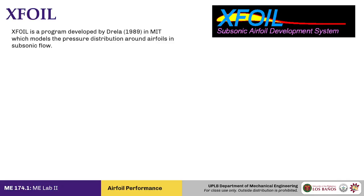It does generate fairly accurate results, especially in the subsonic regime. So sometimes you don't have to go to CFD immediately, because if you compare the data for CFD and Xfoil, sometimes there are flow regimes where Xfoil actually wins in accuracy over CFD, and that means a lot because CFD is very intensive on your computer.